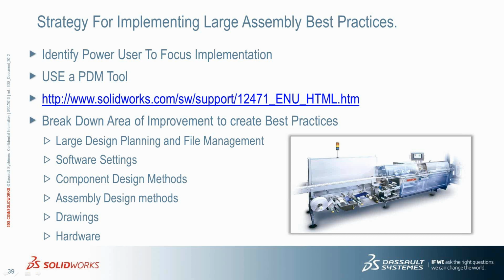What is the alternative to extruded text when text is necessary? So here's what I'll say about that. If you need text on a part drawing, then put text on your part. But if that part goes into the assembly, create a simplified configuration so that text is suppressed. Because in the assembly, you don't need to see it.